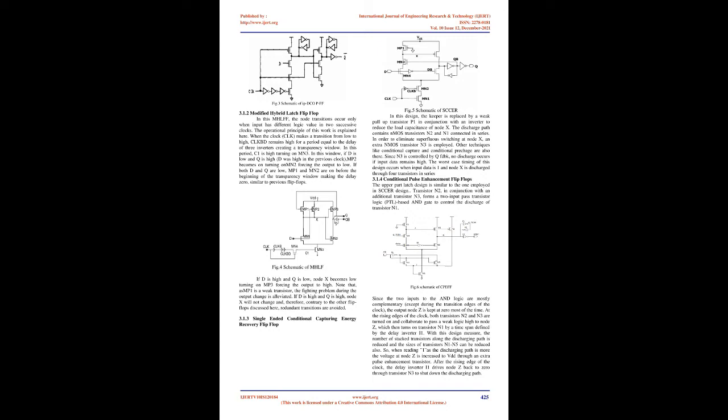3.2 Basic explicit pulse triggered flip-flops. 3.2.1 Explicit pulsed data close to output. The schematic of the explicit pulse data close to output flip-flop, EPDCO, which is shown, is considered as one of the fastest flip-flops due to its semi-dynamic nature. It uses the delay of 3 inverters to generate the pulse at the double edge of the clock.